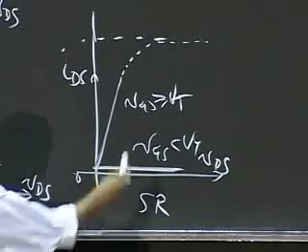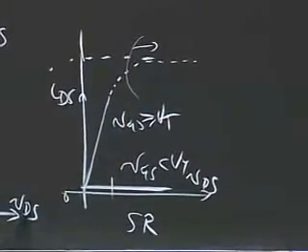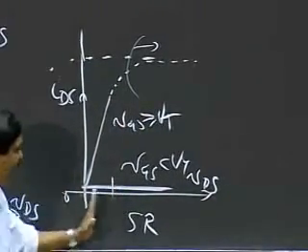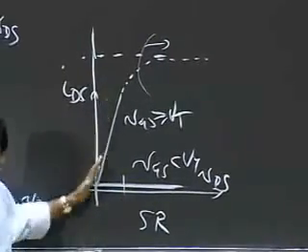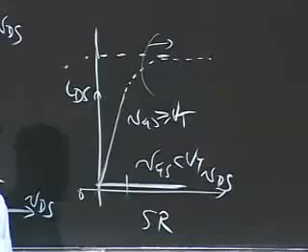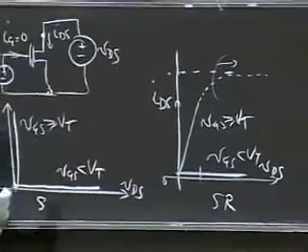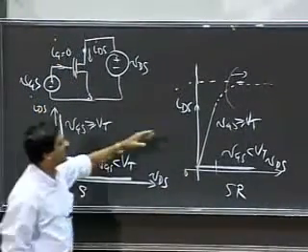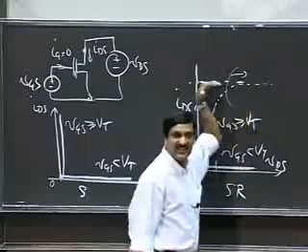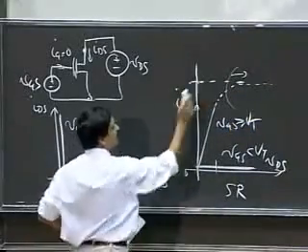And so I'm going to look at this region of behavior. Notice that what we looked at so far was the behavior for small VDS. Oh, it kind of looks resistive. But when I pump up the VDS, really whack this node really hard with a much larger VDS, the guy says, oh, I give up. The current saturates out and flattens out and holds the value steady at some value.